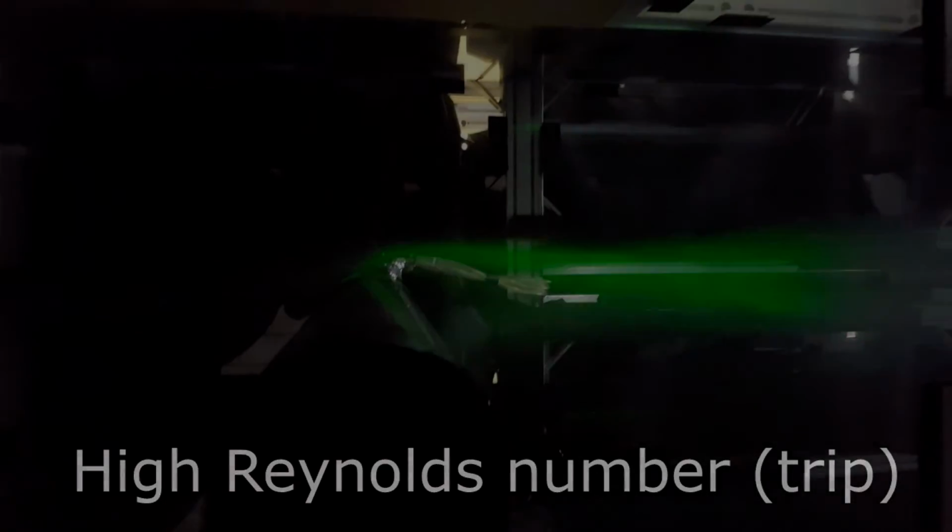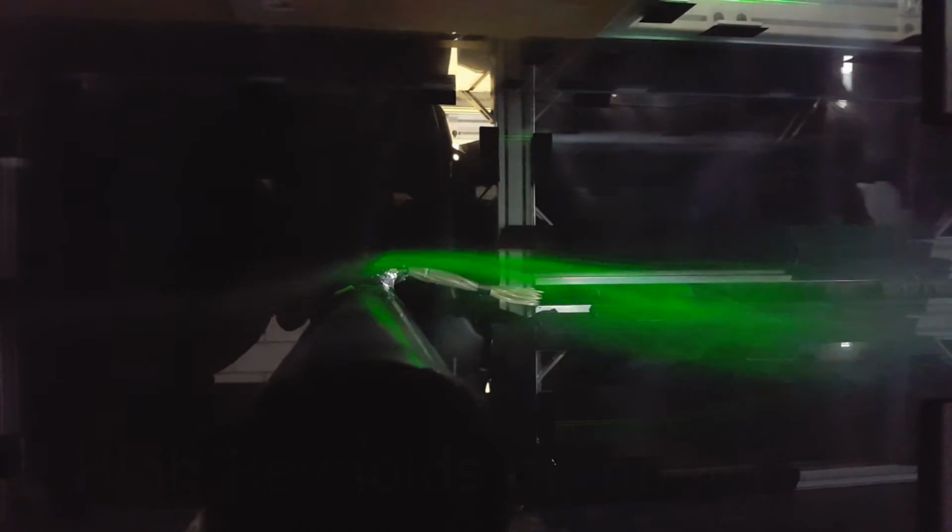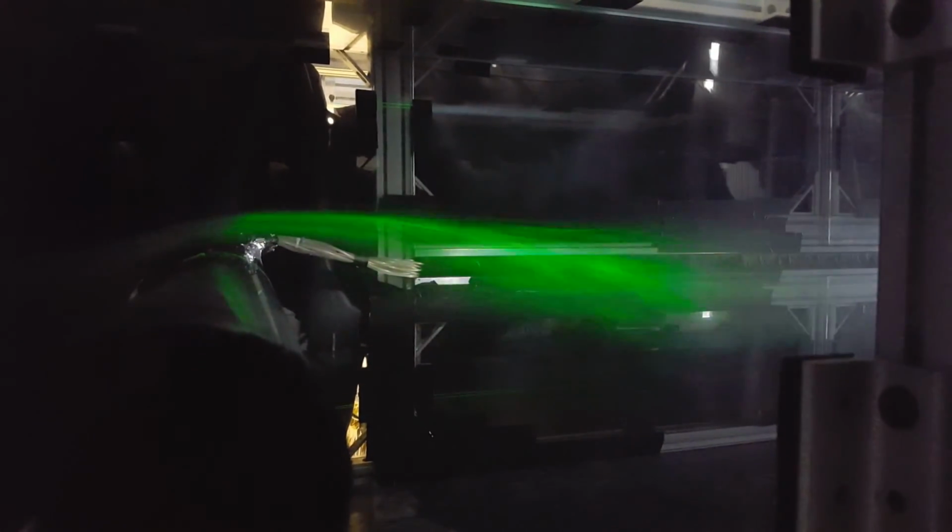The smoke can also be seen sticking and wrapping around the top of the cylinder as the wind flows over it. With the addition of the tripwire, flow separation occurs further up on the cylinder due to the surface roughness it adds, and the smoke detaches from the cylinder closer towards the front of the cylinder than it did with a no tripwire case.